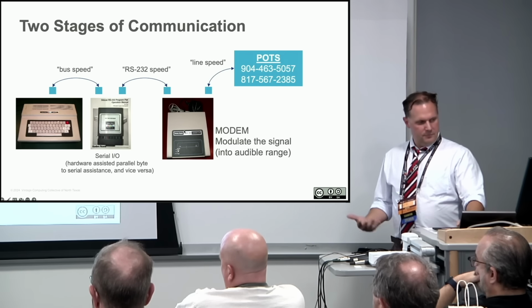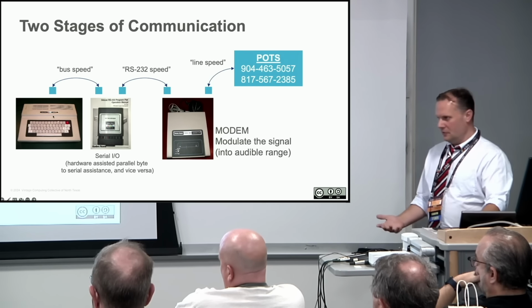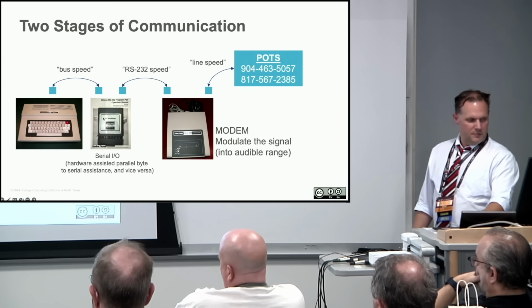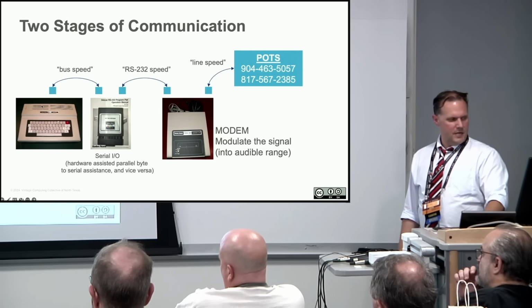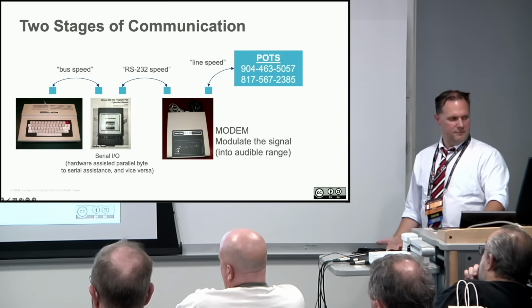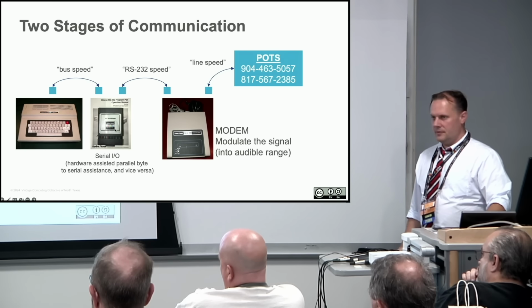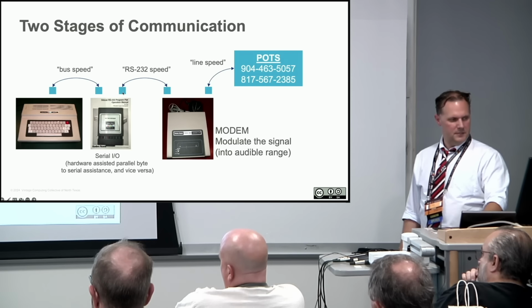So speaking of that, with modems, if your Color Computer doesn't have a built-in UART, you have to add one. Through the expansion cartridge, it had the serial I/O card that had a serial I/O on board. I have some videos about it where I've tried to use it, and it was really limited to 1200 baud. This thing can get you up to 9600 baud reliably, but it's talking at bus speed, even though it's a cartridge going in there, basically bus speed.